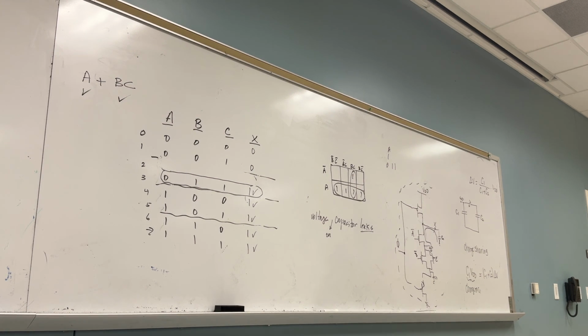You lost me here. Did you lose me? Oh. One more time, please. What is the initial charge on C1? Before you apply the input, during the pre-charge, what is the charge on C1? It's C times VDD. It charged all the way to VDD. But when the switch closes, which NMOS is working? A1. This one.